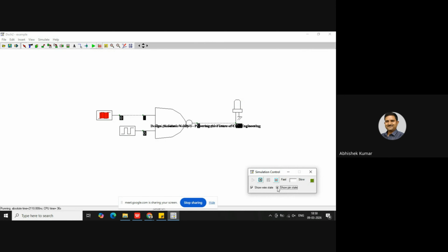Okay, so now here you can imagine that the input is logic 0 or logic 1 as the waveform is coming. So when B is coming at 0, for the combination 0 0, output is high, that is 1. For 1 and 0, output remains 1. For 0 and 1, it is 1, and for 1 and 1, output is going to remain 0. So the output we have generated from this circuit and the output of the NAND gate are the same. If both are correctly matched, then we can understand, yes, our simulation is correct.